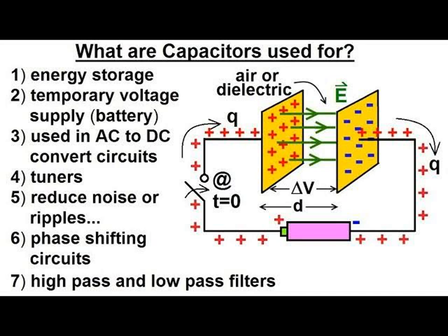So by the time you adjust, by the time you tune, by turning it clockwise or anti-clockwise, it increases the surface area of the plate or decreases the surface area of the plate so as to either increase capacitance or reduce capacitance. Remember, increase in area increases capacitance, isn't it? Decrease in area decreases capacitance because capacitance is directly proportional to area, but inversely proportional to the separation distance between them, right? Good.